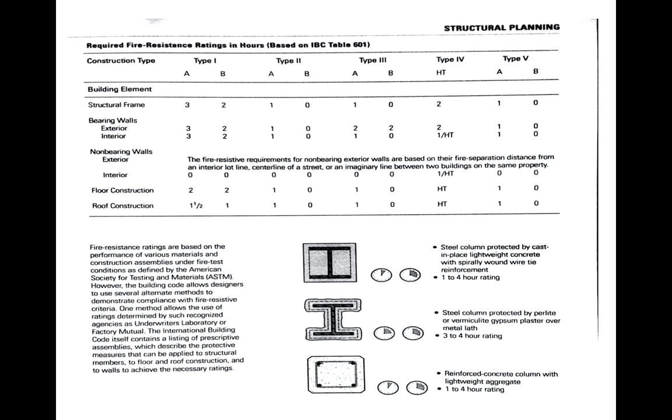And the idea there is that a fire is very unlikely to jump 20, 30, 40 feet out from one building and impact another. It may damage that exterior wall, but it's not likely to ignite anything within the next building. This is an innovation that you can imagine came around when the curtain wall began to be a popular device in the 1950s, when we stopped making the exterior walls of tall buildings out of bearing walls and started making them out of these thin glass skins.